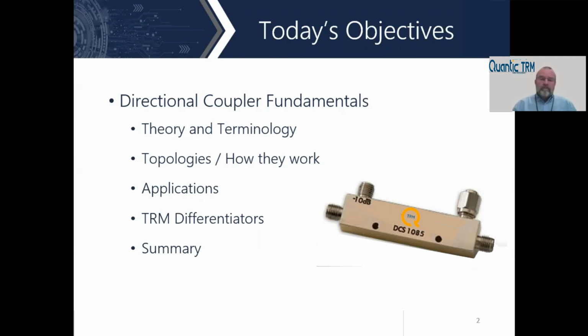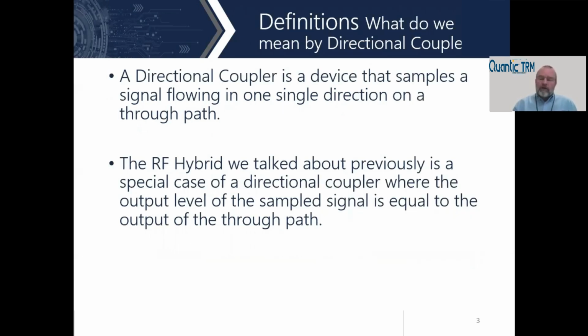Thank you, Shaun. And maybe next you could define couplers in a more technical way compared to that simple definition that I'd given a little earlier. Sure. So a directional coupler is a device that samples signal coming off of a line. It couples energy. By the word couple, it could theoretically mean almost any coupling value, although in this definition, it usually means a small sample. You're coupling just a little bit of the energy off there. And by directional, it means that it only picks up energy flowing in one direction on the line.